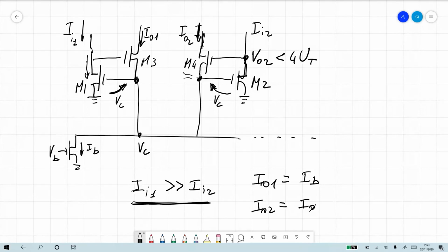What happens when they're very similar, like you have a Gaussian bump, and around the center of the bump you have similar currents? What happens if you have small differences? But first I wanted to be clear what happens if you have large differences. It's also an easy case, but it's good if you understand what's going on. You bring transistors in and out of saturation, and because you do that, the winner absorbs all of IB, and the losers have basically zero current.